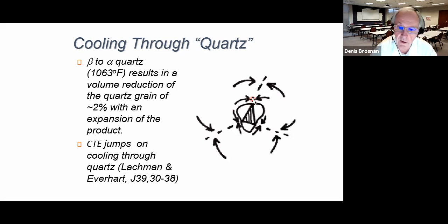But further inland, in these early times, they used updraft kilns because they didn't need as much temperature. So brick makers are typically going to try to limit the amount of quartz that's present in the body because they know it's going to give them cooling problems, susceptibility to cooling cracks.